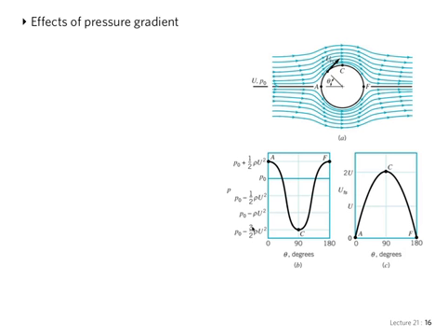And I did mention there briefly that this didn't apply if you have a curved surface, because basically the argument that we made, if you recall, was that our neglecting of various terms resulted in the conclusion that the pressure was going to be dictated by the inviscid area. And in the inviscid area, the pressure changes according to Bernoulli's equation. So if there are no curved streamlines, there is no change in pressure. And so the pressure was constant everywhere. But in here, there are curved streamlines because the body is curved and the flow must adapt to the body. And so there are going to be pressure changes, unlike the flat plate.